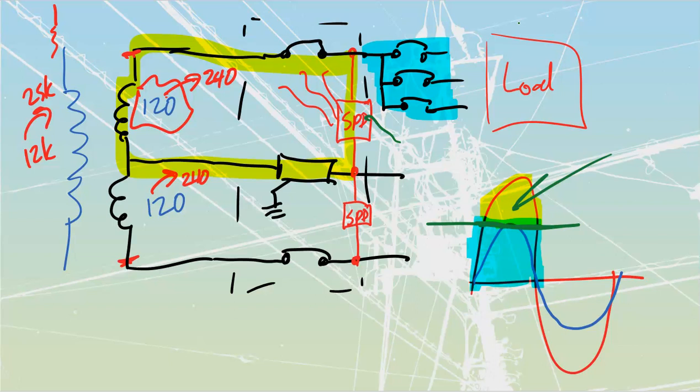And it's basically a type of diode that's going to maintain a specific value of voltage over top of its output. Now, a Zener diode does always need to have a bleed-off resistor in line with it, right? Because if the Zener is going to hold its value of voltage, you need somewhere to put the other value of voltage. These surge-protected devices are going to incorporate that, and it's going to be a high wattage one, so it can bleed that off relatively quickly.